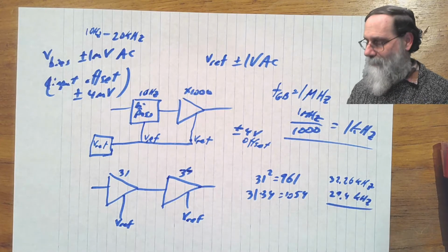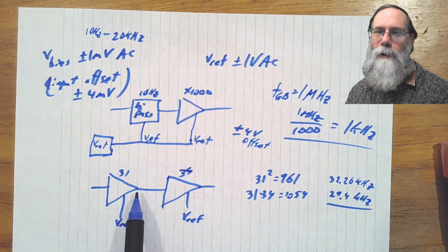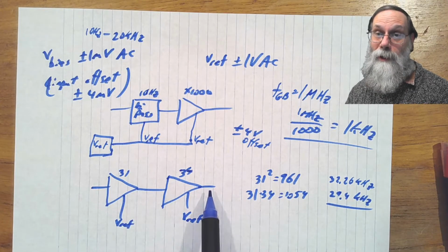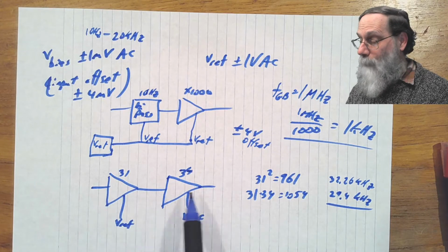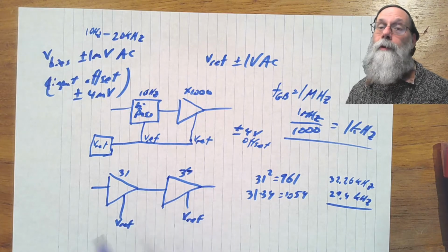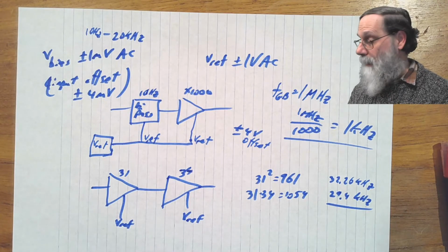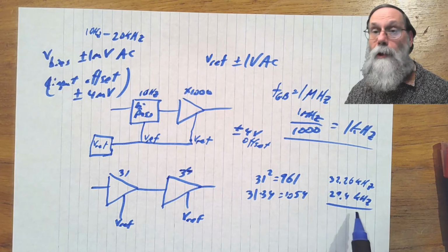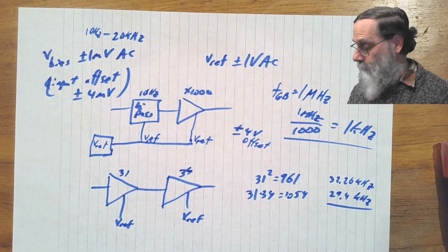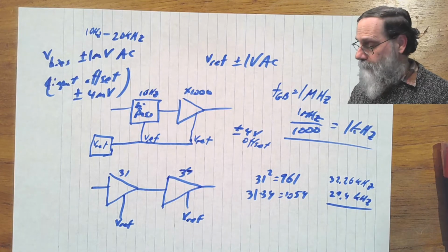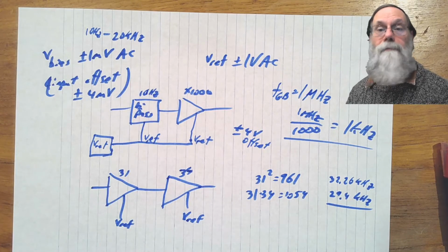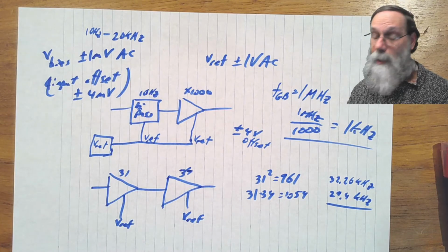But then, if you have a gain of square root of 2 over 2, and then another gain of square root of 2 over 2, at what would have been the corner frequency for each amplifier separately, you'd only have a gain of a half at that. But because these two aren't happening at the same place, it's basically just the lower corner frequency here that's going to determine things. But that's a good deal more than our 20 kilohertz. So this looks fine in terms of gain bandwidth product.